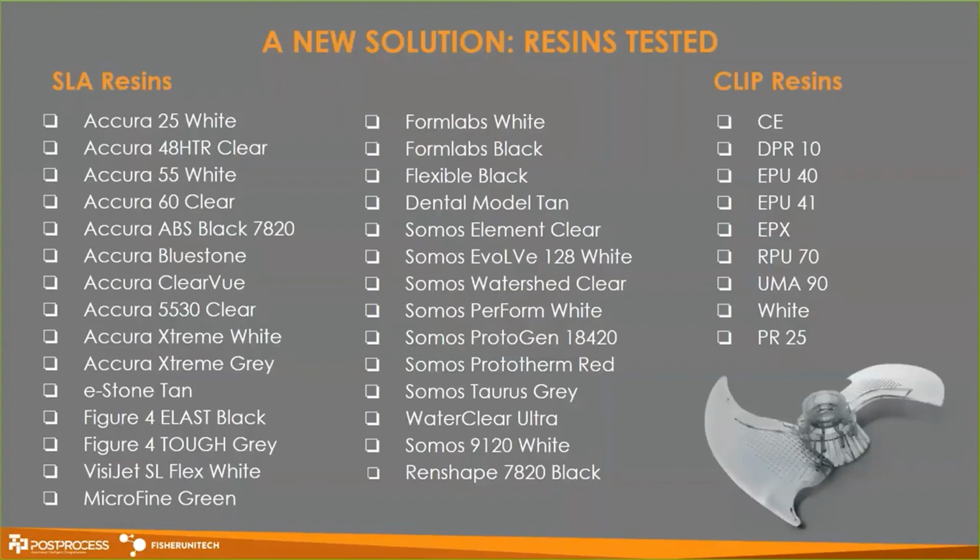So we have a question here about how often the detergent needs to be changed. So that's really going to depend on the volume of your throughput. So one way you can tie to that is depending on how much you're doing, how many grams of resin in solution. So the one slide that I mentioned was we can handle up to 30% resin in solution, so you're able to use it up until that level of saturation. I can't give a particular timeline because it's really going to be heavily dependent on what you're post-processing.